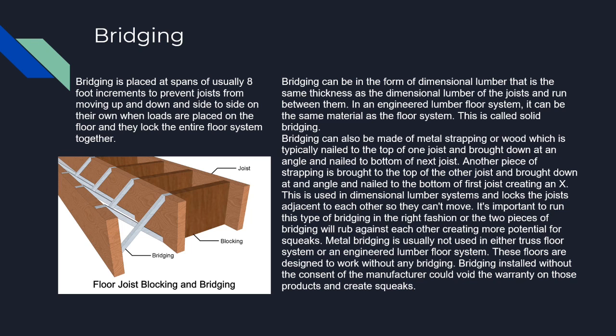Metal bridging is usually not used in either truss floor systems or engineered lumber floor systems. These floors are designed to work without any bridging. Bridging installed without the consent of the manufacturer could void the warranty on those products and create squeaks.